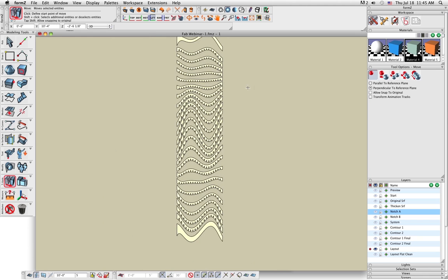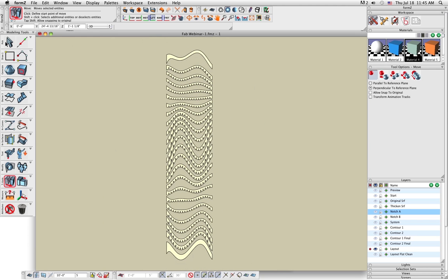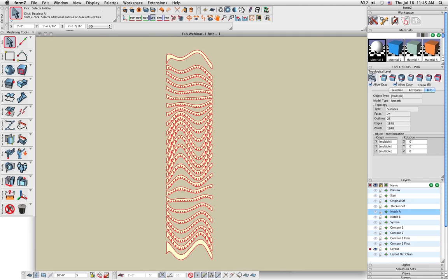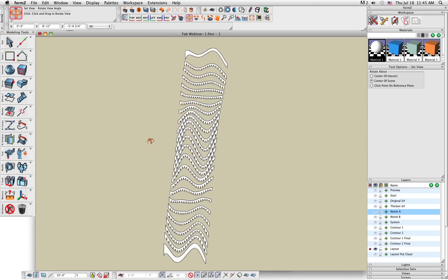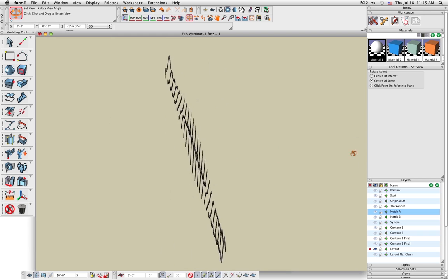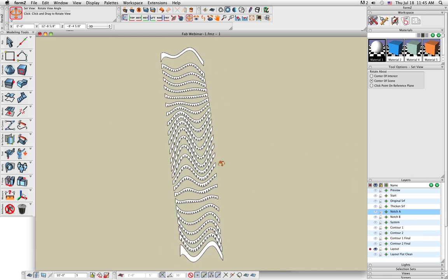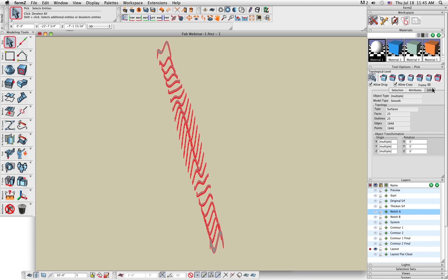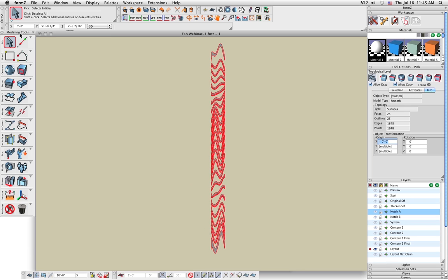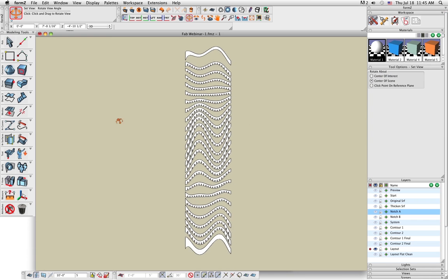So I have the pieces here, and what I'm going to do now is go through and make all the pieces flat on a certain plane, because when pulling the pieces apart it doesn't put them on a flat plane, so they're still floating around in 3-dimensional space. So I'm going to select all my objects here on the screen, and over here in the tool options area under the info tab, you can specify a specific X, Y, or Z increment. So here I'm going to click on the X input, put 0 in as my X input, and there you see it takes all the objects and puts them on the 0 plane of that axis.